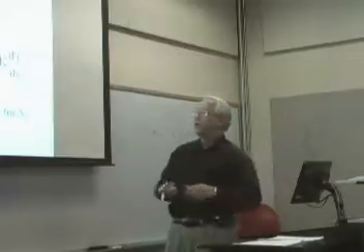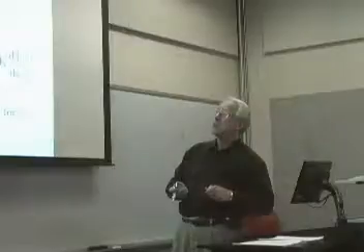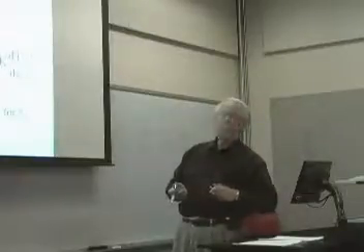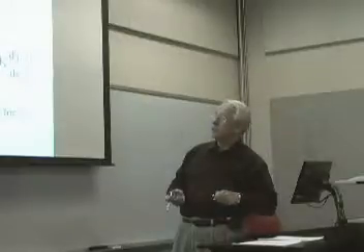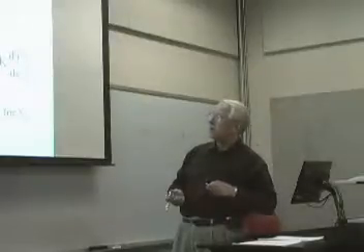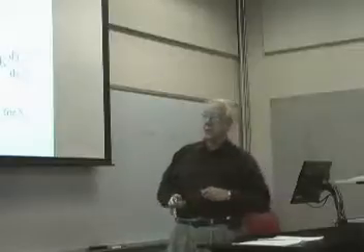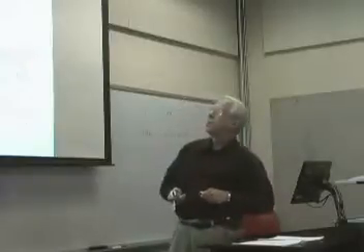So this is what the computer is doing when you set this up, and it goes through and it evaluates all these shape functions. That's what all these terms are right here. And so it just does a simple integration. What you wind up with then, as this thing reduces down, are a bunch of little matrices.